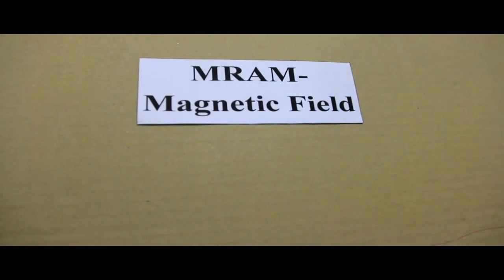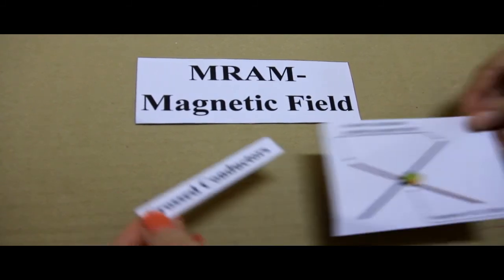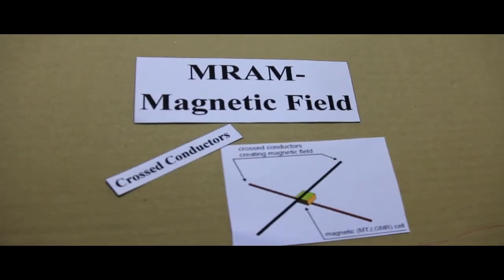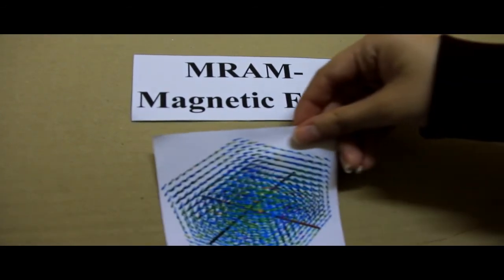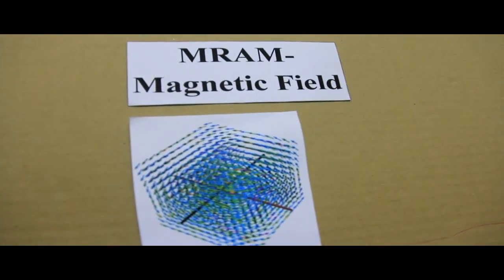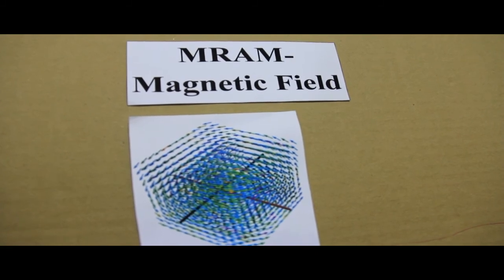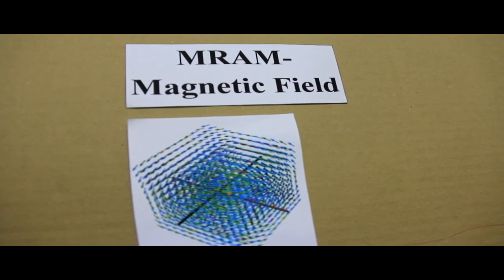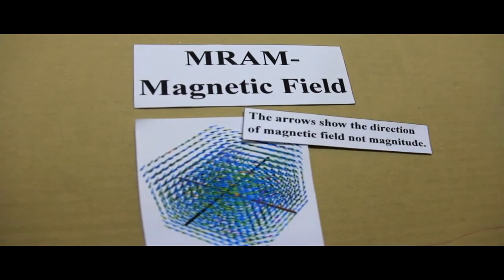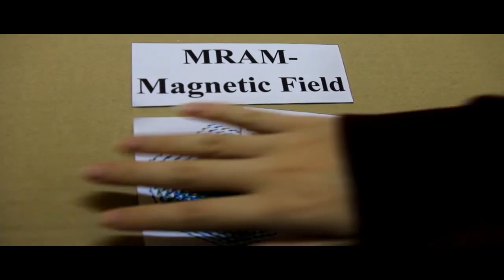MRAM, magnetic field. To produce the magnetic field, which is spatially selective, different arrangements of conductors can be used. The most obvious is the use of crossed conductors, usually stripes. The magnetic field created by the single line is too weak to switch the magnetization of the free layer. Combined action of two conductors creates the field which is strong enough to switch the moment direction of the memory cell. In the diagram, the arrows show the direction of magnetic field, not magnitude.